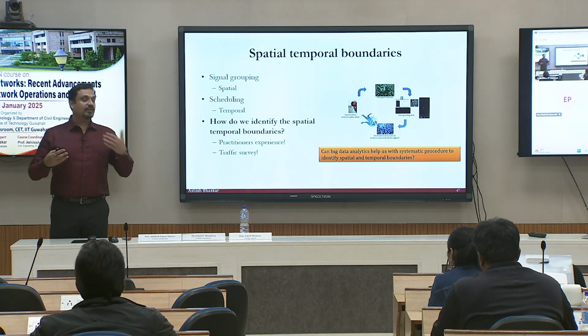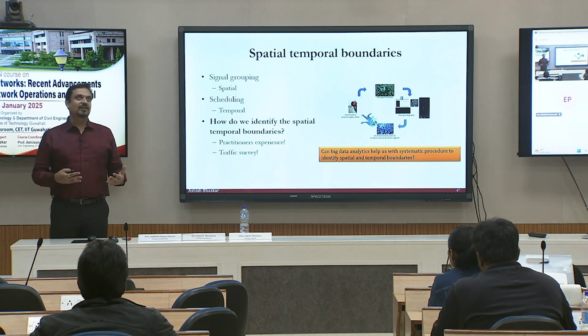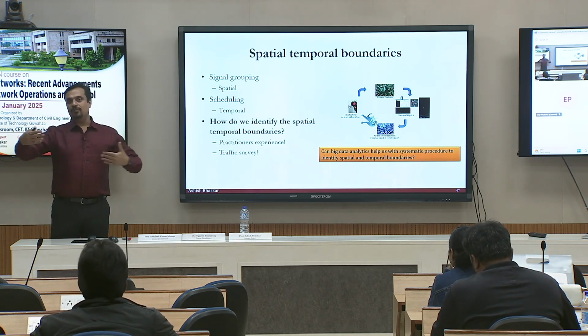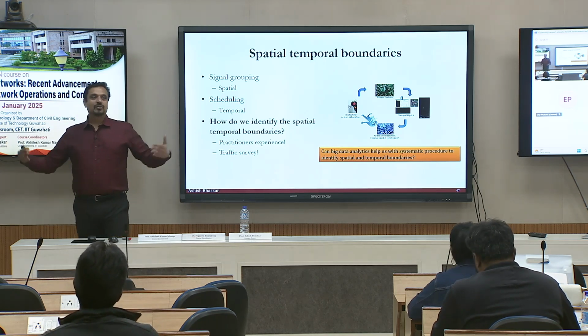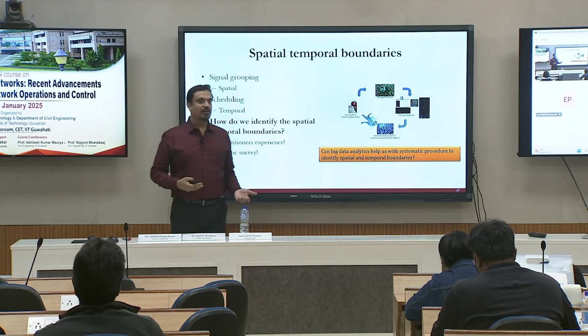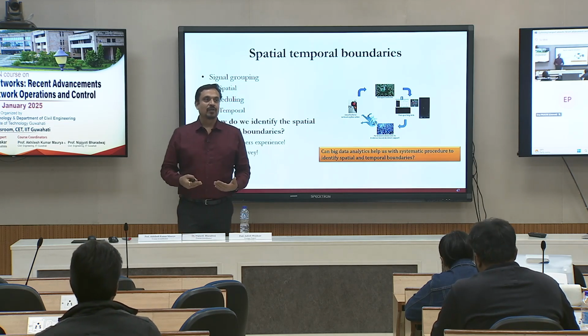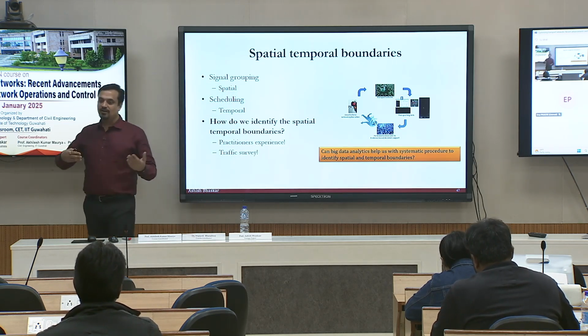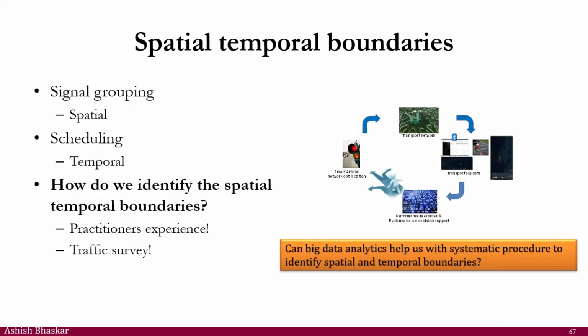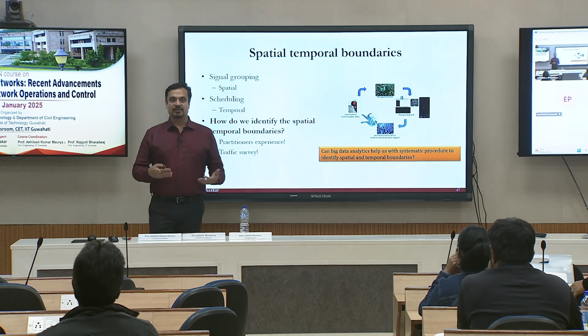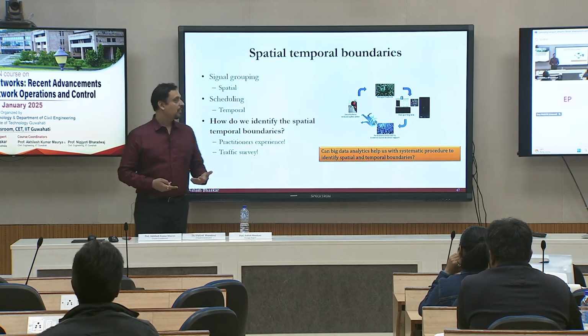So first thing, like yesterday we talked about signal timing design, right? Not optimization. You know your demand profile. You know the road geometry definitely. Intersection geometry you know very well. You know how much demand is expected from different approaches. You define your phases considering the requirement for that intersection, and then you give a green value for an approach based on the demand it is going to serve.